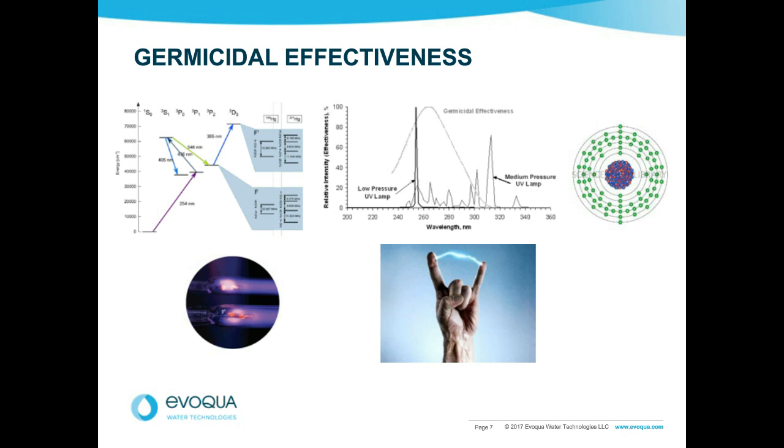I would say that we're working in collaboration with some very effective filters. We use the Vortisand filter a great deal before the UV and particularly before membranes. So filtration is a critical part of making the UV performance optimized and indeed optimizing the membrane performance. So I'd look to a high process performing filter like a Vortisand, or even a VAF screen before the Vortisand, to make sure that the water has been properly prepared for UV and then properly prepared for the RO membrane.